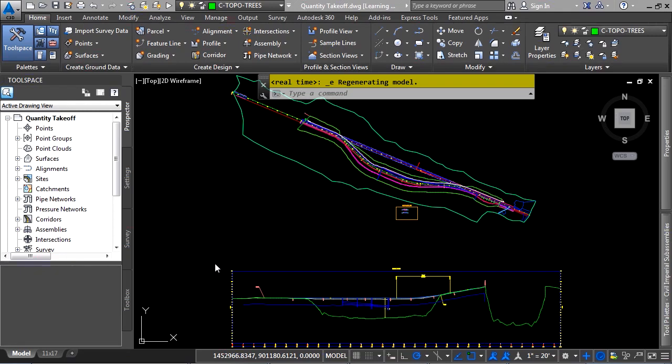Incorporating pay item information correctly into design plans, including plan sheets, summaries, and bid documents, is a major task for designers. You can use the QTO Manager functionality to automate the pay item process to reduce those errors. Pay items can be associated to AutoCAD lines, open or closed polylines, blocks, or any AutoCAD or Civil 3D object after they have been created.